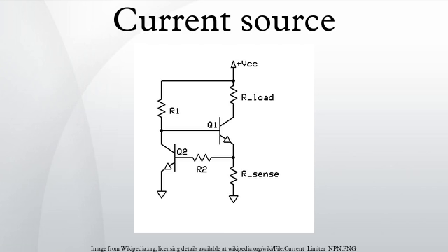In these circuits, an op-amp compensates the voltage drop across the load by adding the same voltage to the exciting input voltage. As a result, the op-amp inverting input is held at virtual ground, and the combination of the input voltage source, the resistor and the supplied op-amp constitutes an ideal current source with value IOUT equals VIN/R. The op-amp voltage to current converter in Figure 3, a transimpedance amplifier and an op-amp inverting amplifier are typical implementations of this idea. The floating load is a serious disadvantage of this circuit solution.